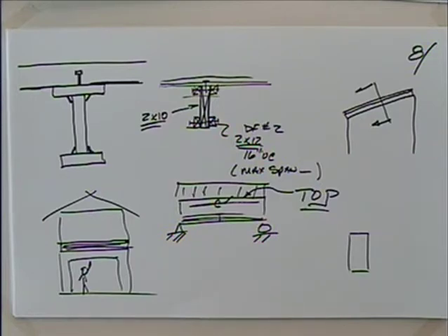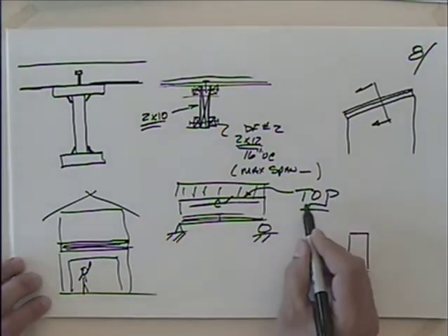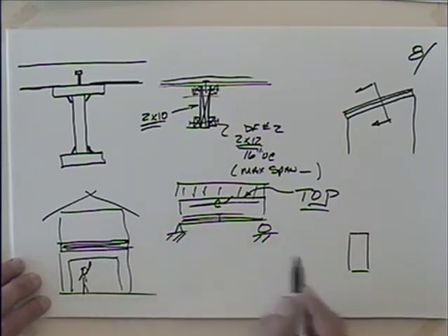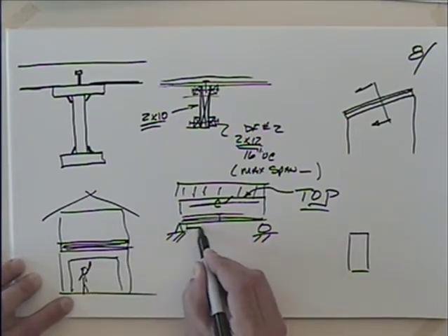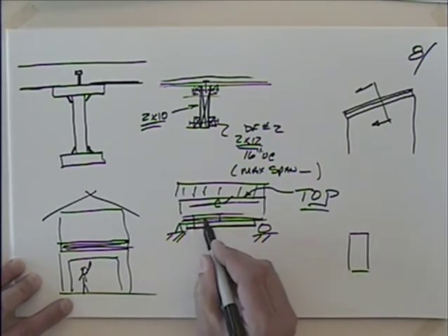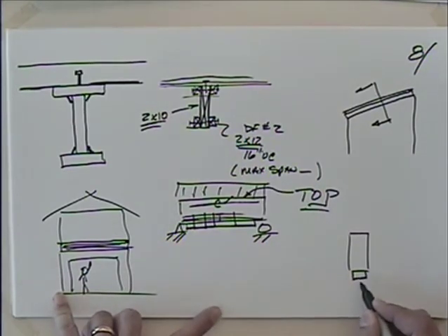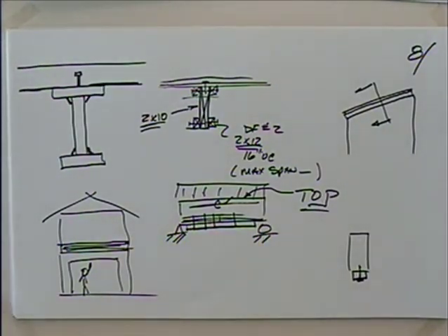I worked with someone that from the time they got the building permits till the time they handed the customer the key, this was in the building boom before things fell apart, was less than 30 days. They built a house in less than 30 days. Okay, so it moved right along. So you have a problem here. Okay, you don't want to tear that beam out. You got to tear half the house out to get that beam out. So what do? Well, you come in here and you put a piece of steel on this thing and you lag it to the bottom of that, so you effectively build this composite beam. Okay? And figuring out what your lag spacing is exactly what you did in the previous problem.